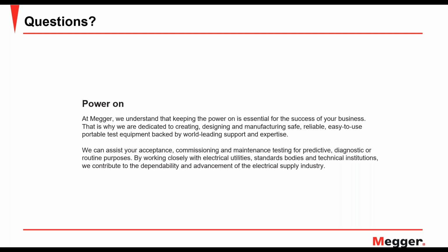And while I have the little podium, so to speak, virtual podium, let me just mention one other thing about the FRAX, which is pretty cool. I know that Sanket had talked about grounding and the importance of grounding in an SFRA test and analyzing the results, particularly in a very high frequency range. One thing that the Megger FRAX has as well is a ground loop detecting circuit. So basically, it's going to give you a green light if it detects that your grounding circuit is good, and it will alert you to those circumstances where maybe you don't have the ground tethered to the bottom of the bushing flange of a connection. Maybe it's been painted and that is a really good connecting point, and you don't know it, but you don't have a very good ground. It does.